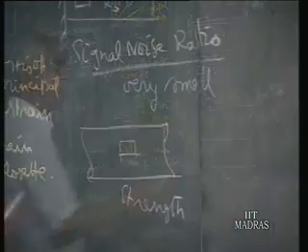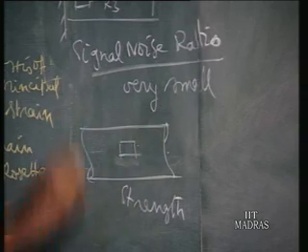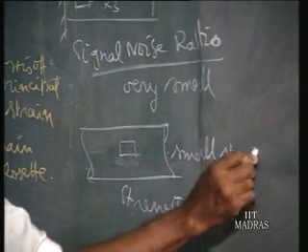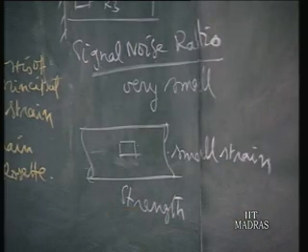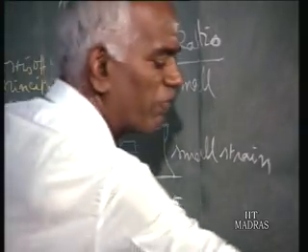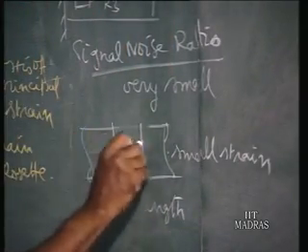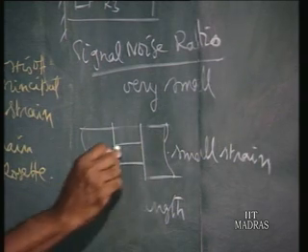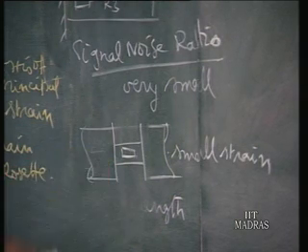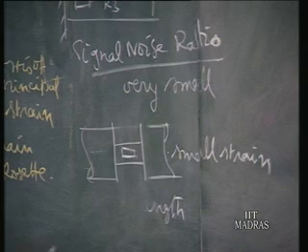If it has been designed for strength, and you paste a strain gauge on this, you will have only a very small strain. In that case the voltage produced from the bridge will be very, very small, and the signal to noise will be small. So what you are supposed to do is weaken these cross sections, make it a smaller dimension, and then put your strain gauge here. This is a little bit of a problem, in the sense that you will find the dimension will be small for a larger strain and you cannot paste it.